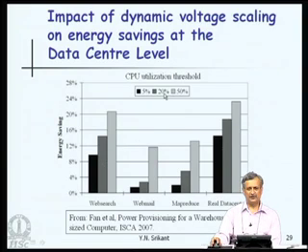whereas if I can tolerate 20% slowdown in my CPU speed, in other words my application takes 20% more time, then I get more, maybe 15% or so, and if I can tolerate 50% slowdown in my application, I can actually get much more saving, 20% or more. But obviously, we cannot sacrifice performance to such a great extent. So, we may be somewhere between 5 and 20% as far as DVS is concerned. Normally, it is not more than 5-6%.